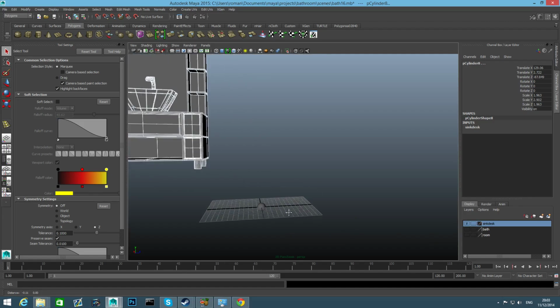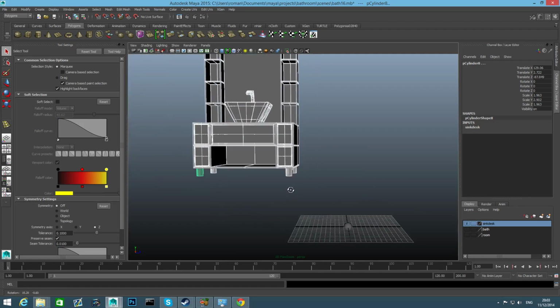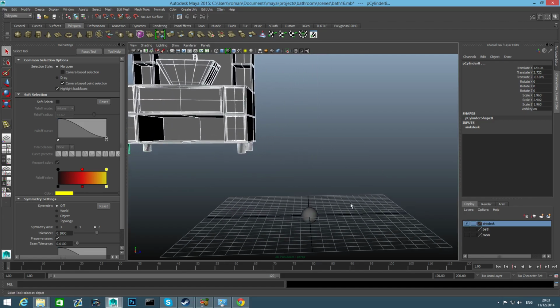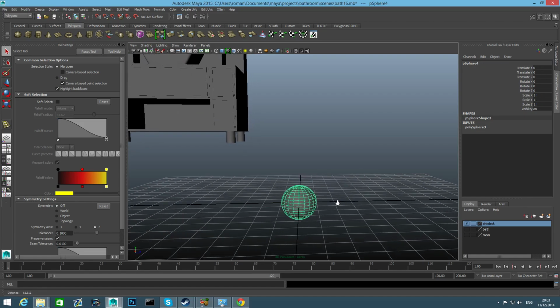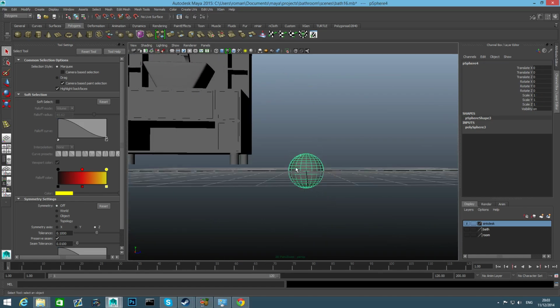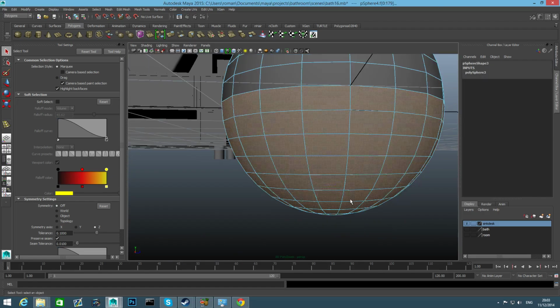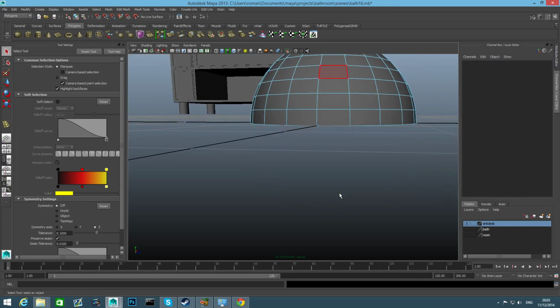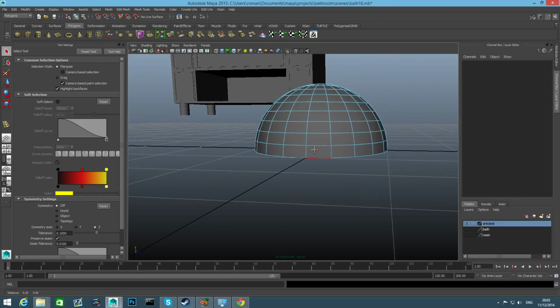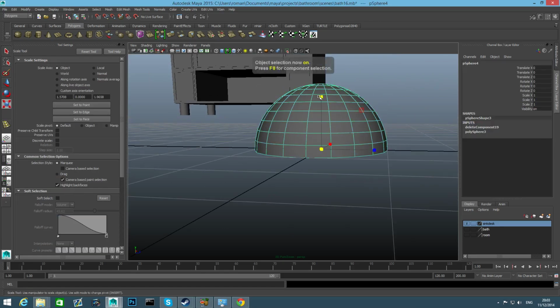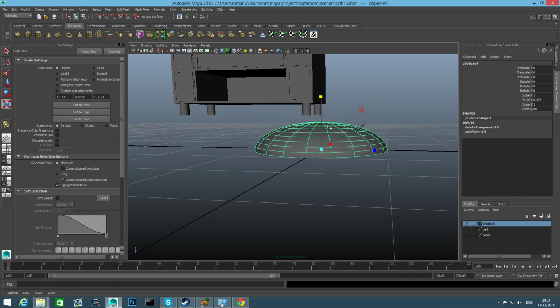things here. Let's keep the sink there. Yeah, the legs are there, and with this I'm gonna right click, choose face, grab those faces, half cut of it. Let's press F to zoom on it, press delete to delete it, and edge. And first of all, I want to squeeze this down a little bit. I don't want this to be that way.